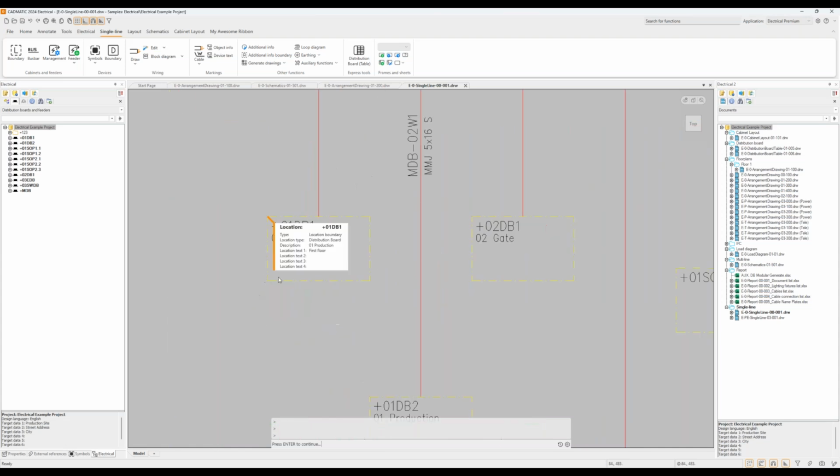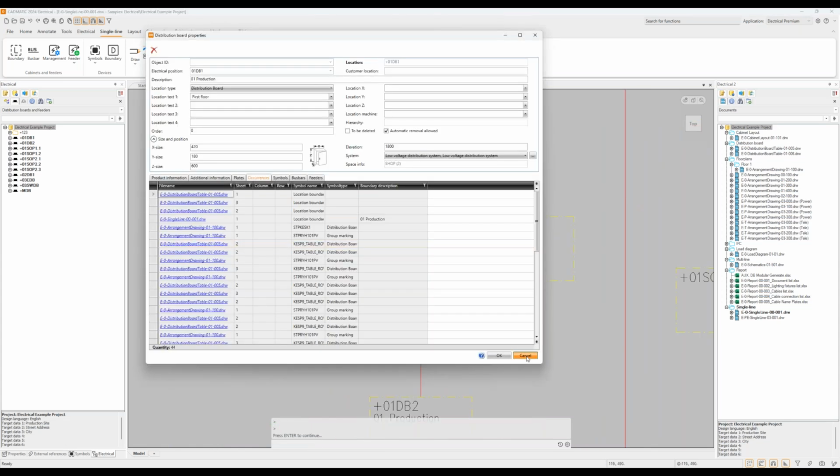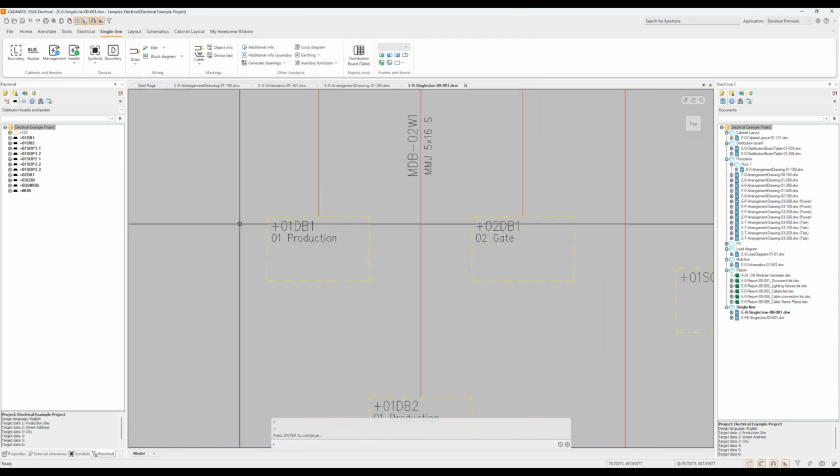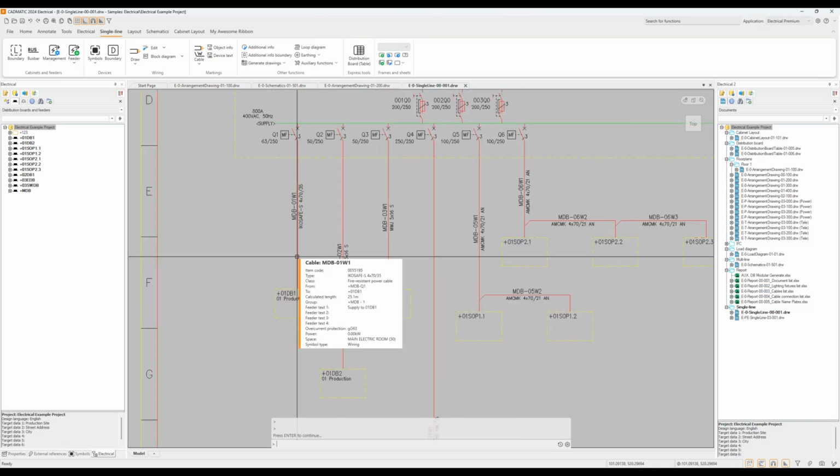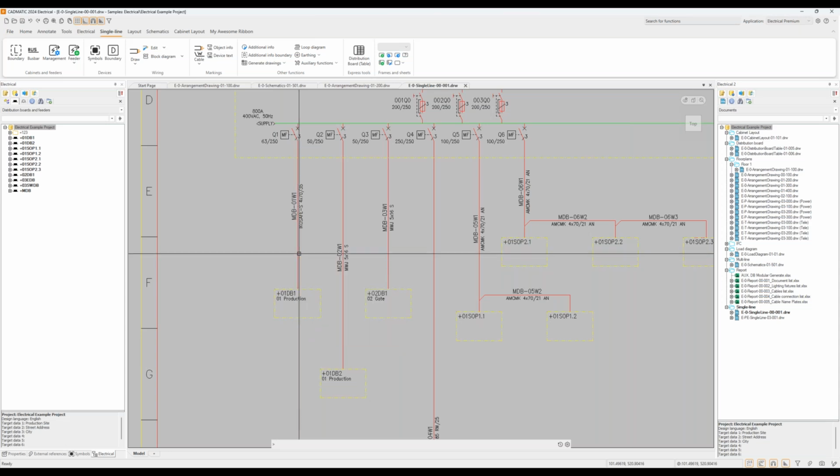And you can see there is this same location again, and there is a cable between the main distribution board and this one, distribution board 1, and that also has the from and to information and the calculated cable length. And that way, now we have the connection, we have the cable length, we have a protection device, we can do the calculation for many things.